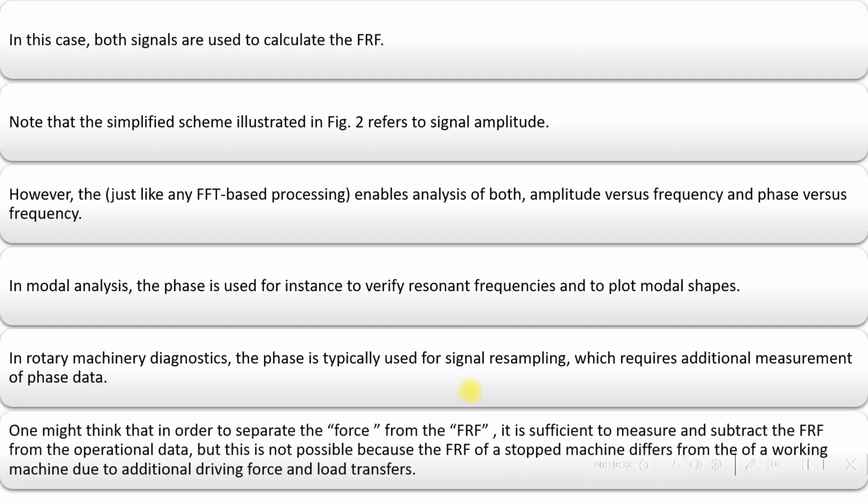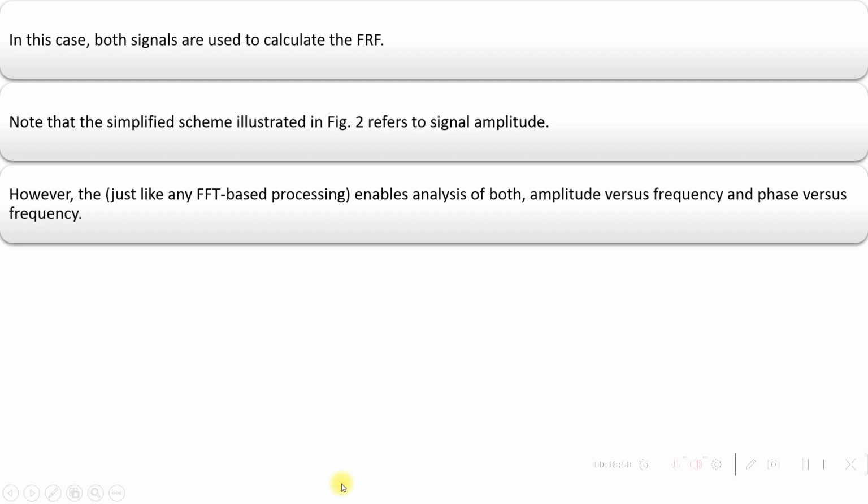One might think that in order to separate the force from the FRF, it is sufficient to measure and subtract the FRF from the operational data, but this is not possible because the FRF of a stopped machine differs from that of a working machine due to additional driving force and load transfers. So you can see here,